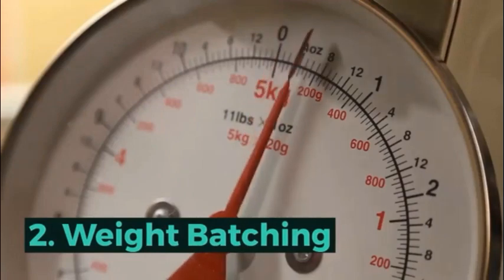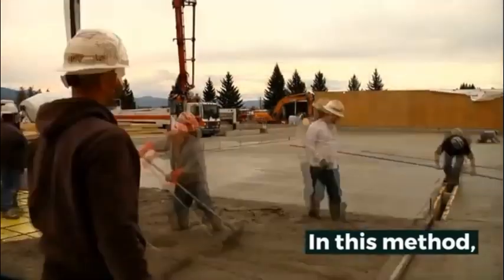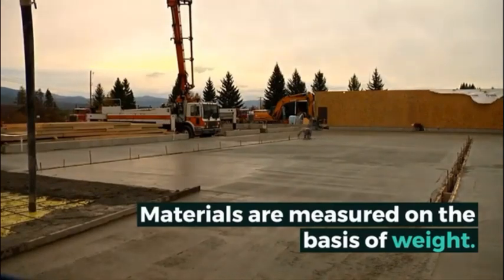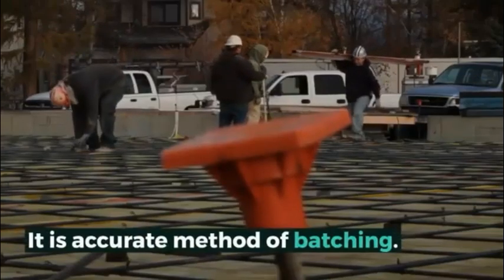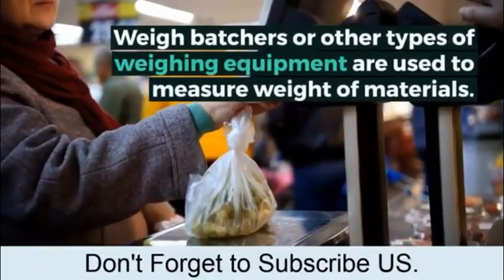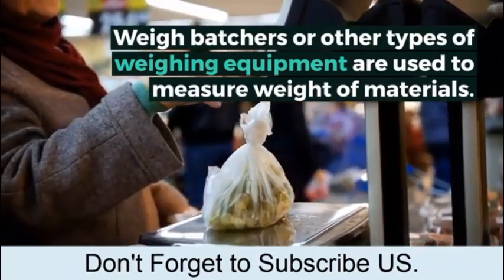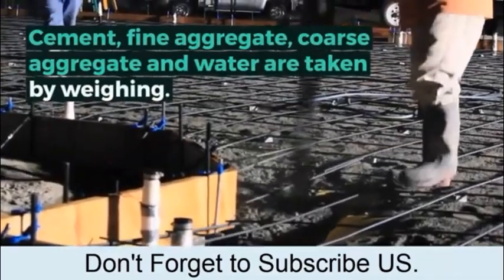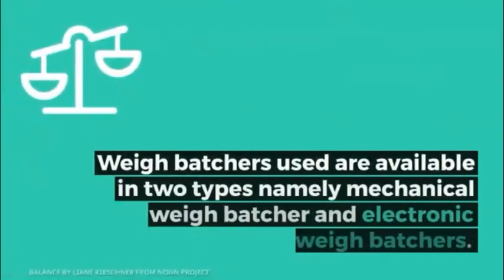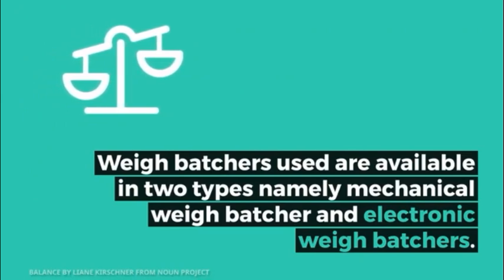Weight batching of concrete. In this method, materials are measured on the basis of weight. It is an accurate method of batching. Weigh batchers, or other types of weighing equipment, are used to measure the weight of materials. Cement, fine aggregate, coarse aggregate, and water are taken by weighing. Weigh batchers used are available in 2 types, namely, mechanical weigh batchers and electronic weigh batchers.